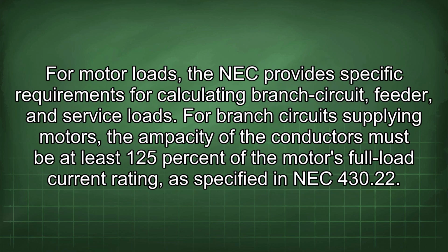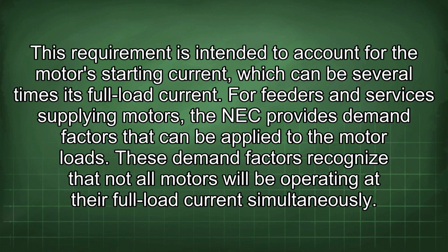For motor loads, the NEC provides specific requirements for calculating branch circuit, feeder, and service loads. For branch circuits supplying motors, the ampacity of the conductors must be at least 125% of the motor's full load current rating, as specified in NEC 430.22. This requirement is intended to account for the motor's starting current, which can be several times its full load current.